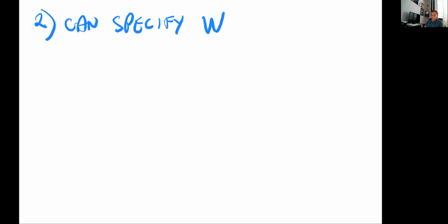And also we could specify the channel length and the width of the transistor, but I'm going to put an asterisk here because I'd rather keep this constant, because the process is optimized for that critical dimension, which is the width of the polysilicon, the geometrical width of the transistor, which is the electrical length of the channel.